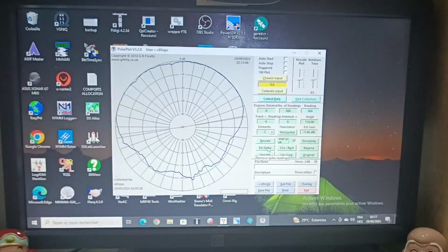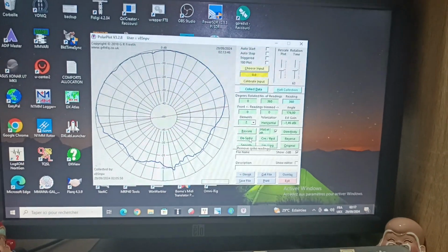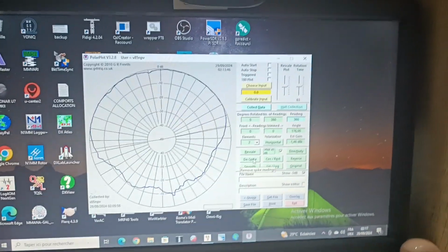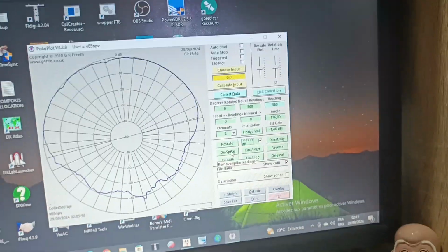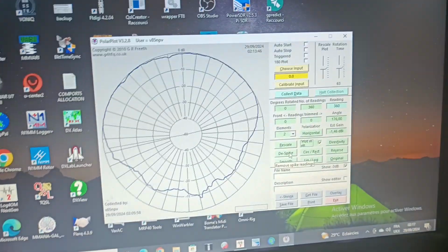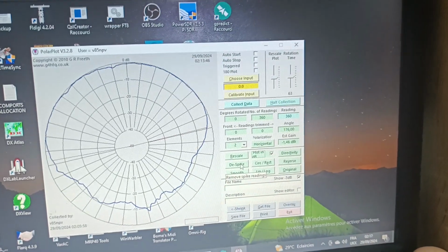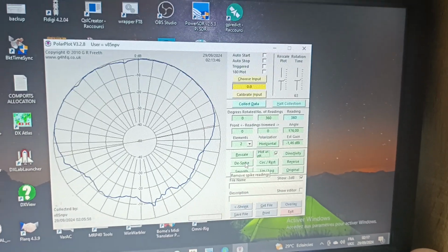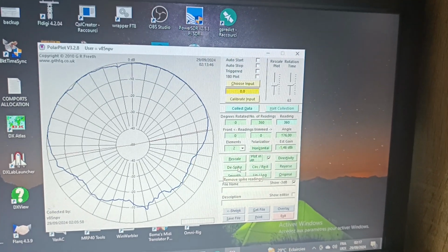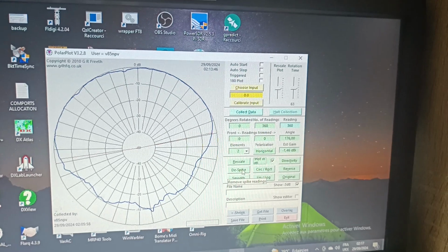For example, maybe to get more directivity, more gain, and so on, because this is a beam antenna. You cannot have both, in fact. You can have a lot of gain but lower directivity, or more directivity, which means more attenuation, front and back ratio, but less gain.